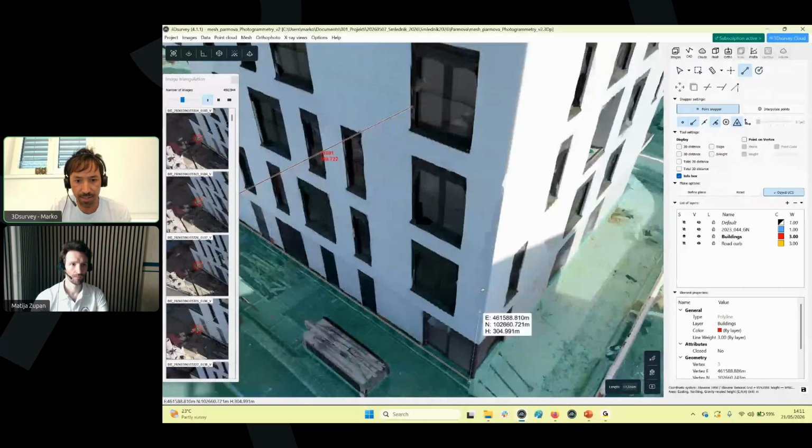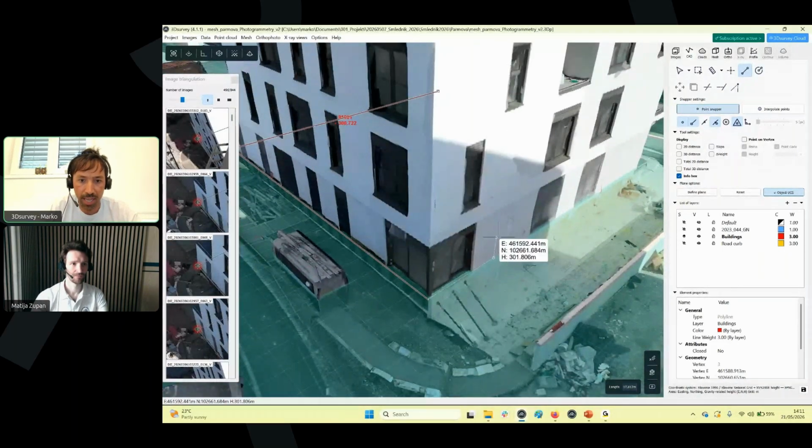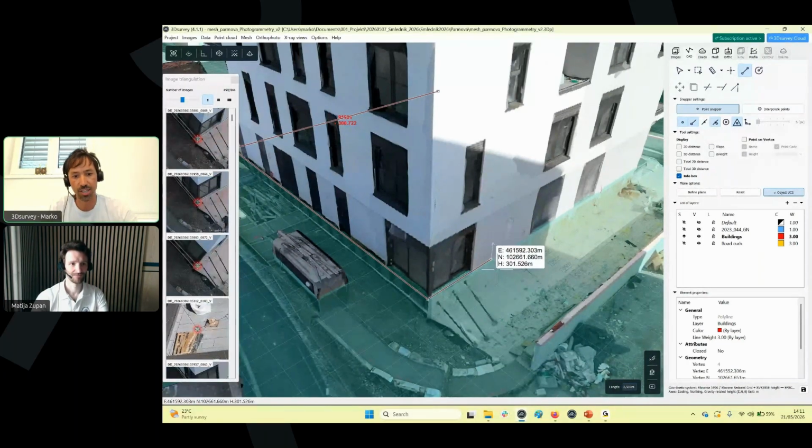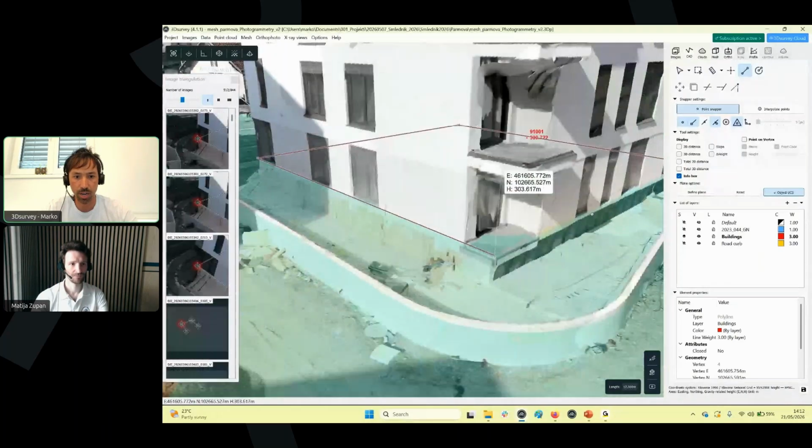And because here is the window, you see the building facade is 10 centimeters away from the window, which is fully normal. And what I can do, I can use my corner up here, or even more accurate, I can snap on another plane of the building and define the line of this front side of the building with help of this. So even if I click here with my left mouse click, you see I finished the line exactly on the same distance I would like to have it. And this way I can go and continue here.